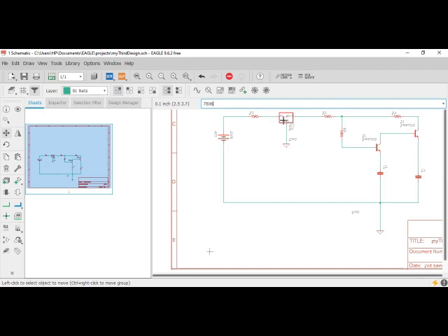Anytime you see a voltage regulator and you see in part of it an indicator, or I should say a nameplate like that, if you see something like a 7806, 7805, 78 means positive, and 06 means 6 volts. If you find it as 5, it means 5 volts voltage regulator. If it is 12, we see that it is 12 volts voltage regulator. So that's how to know the value of a voltage regulator. So we've added this voltage regulator to be a 6 volts one.